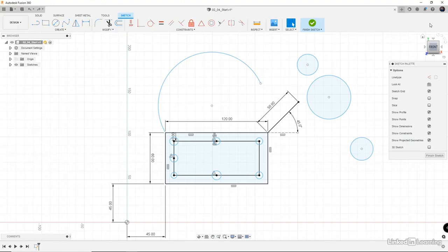Now that we've gone ahead and talked about sketch dimensions and constraints and a couple ways to edit and update them, let's see what we can do with some basic sketch, using those techniques in updating both the dimensions and constraints to drive our sketch. So if we come down here, we can see that we have this rectangle, and that rectangle is fully constrained because it's all black. So we used a 2-point rectangle to create this, and then we referenced it to the origin of the sketch with a 45 dimension, which gave it its full constraint. And then everything is essentially deriving off of here.